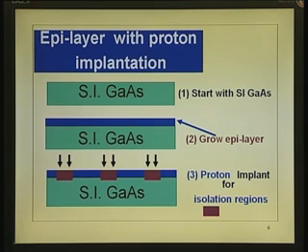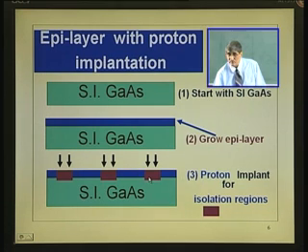In fact, you can turn these in-between regions into regions where the carrier concentration is something like 10 to the power of 11 per centimeter cube. That is virtually semi-insulating. So, you can get 10 to the power of 11 electrons per centimeter cube, that level you can go by bombarding with proton.